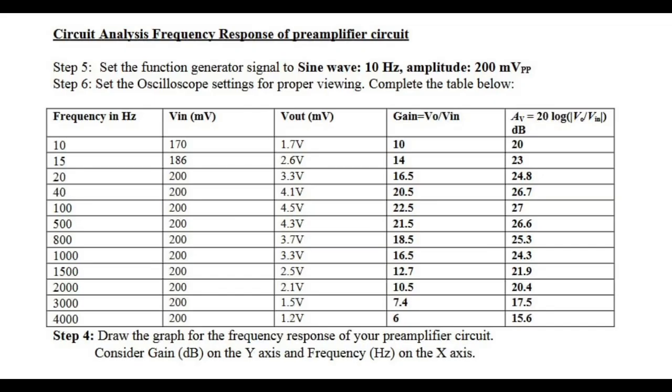Based on this table for the amplifier in stage 1, we can see as frequency increases, the gain will also increase until its maximum of 23 as was calculated earlier on. Its peak frequency will be at 100 Hz, and frequencies higher than 100 Hz will cause the gain to drop. A gain of 23 is equivalent to around 27 dB.